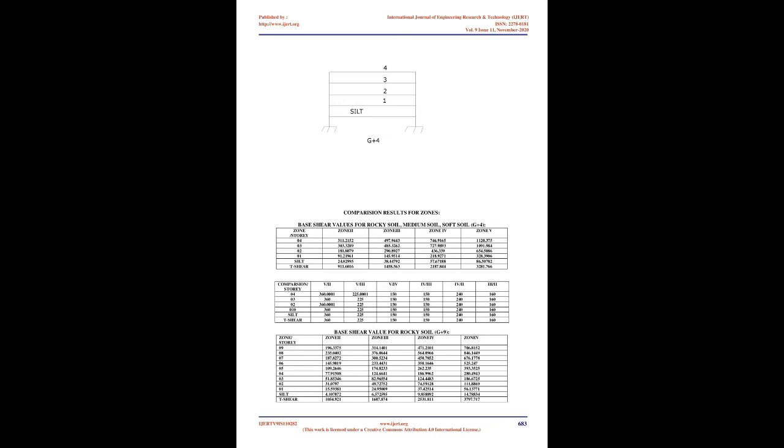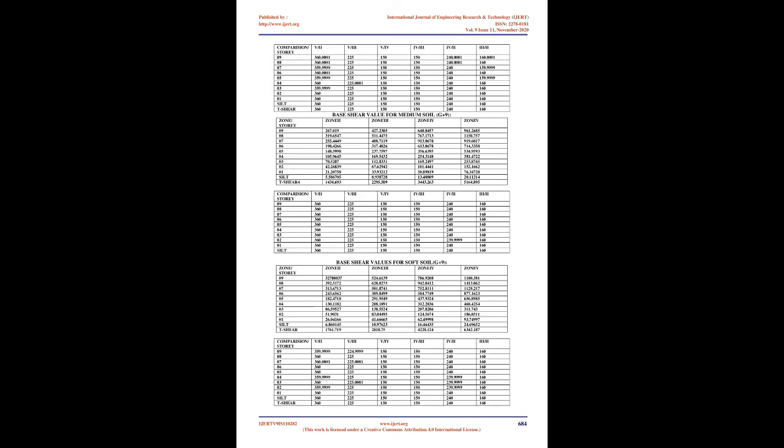Architectural planning of structures. The behavior of a building during an earthquake depends critically on its overall shape, size, and geometry, in addition to the earthquake forces. Buildings with plan irregularities, for example those with reentrant corners such as L-shaped plans on corner plots, and those with elevation irregularities, for example large vertical setbacks in elevation such as a plaza-type configuration in commercial structures, are common. Buildings with plan asymmetry may experience significant torsional motions with even slight eccentricity between the center of mass, CM, and the center of rigidity, CR.